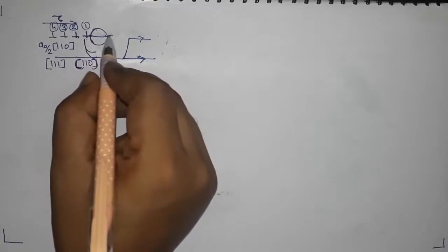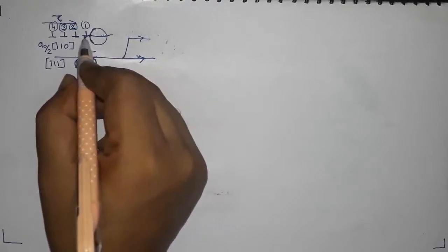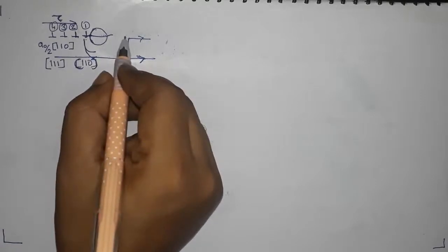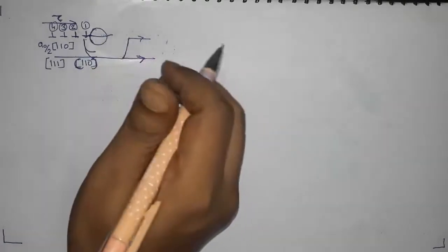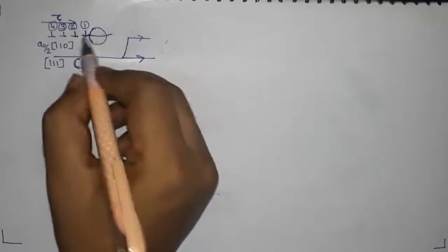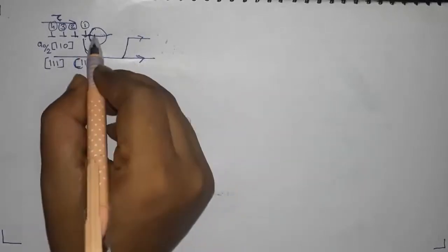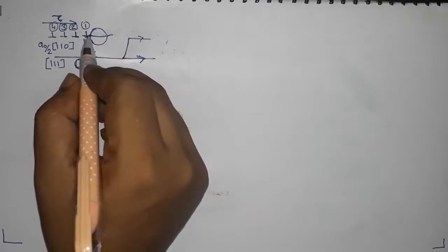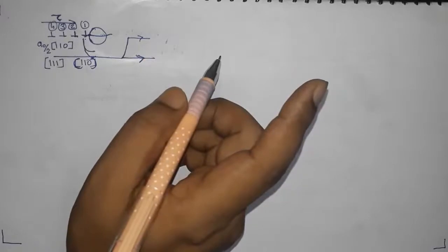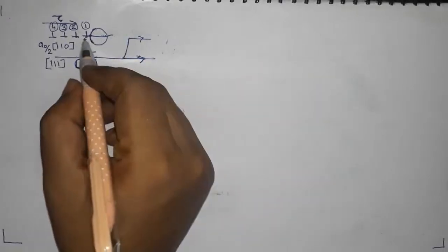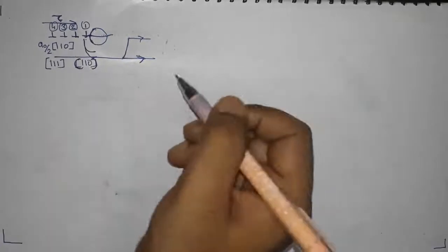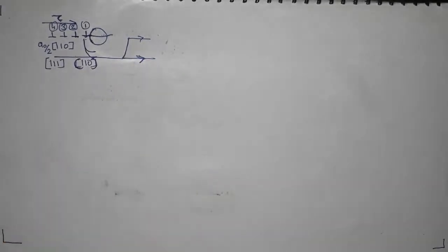Okay, once this precipitate has broken, then the other layer is ready for this dislocation and it can pass through that. Okay, so that will be shearing of the precipitate. If it is a coherent precipitate, then it can pass through. If it is a semi-coherent precipitate, then it can be blocked also. Okay, so this was one of the theories which proposed that because dislocations pile up and you need more stress for them to either break the barrier or pass through by some other means, that's why you need more stress to deform, and that explains strain hardening.